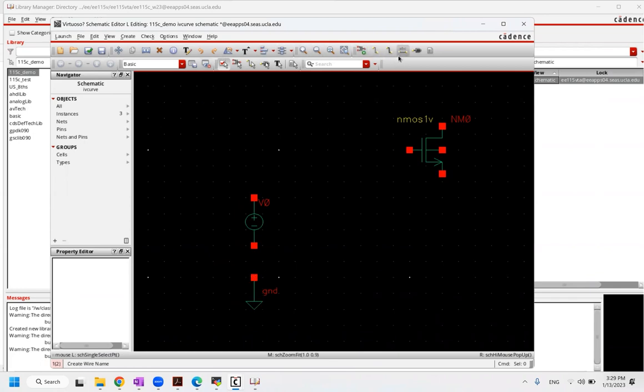Normally what I like to do is not connect all of them with wires. You connect them with net names. For the ground, I don't like to connect it directly to the components, because the net is called GND by default and you cannot change its property. Normally we connect the GND to a voltage source, and from the voltage source we make another net that will be our reference net.